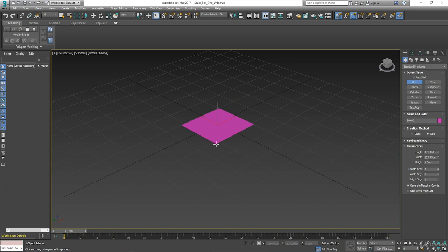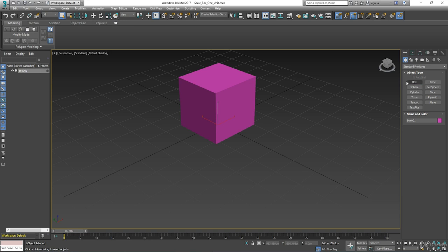Doesn't matter about the size for now. I'm going to show you how to get it exactly right and scale it out so it's roughly the right height. Just left click to cancel, and right click in blank space cancels box making. So that was another way of cancelling box creation mode.